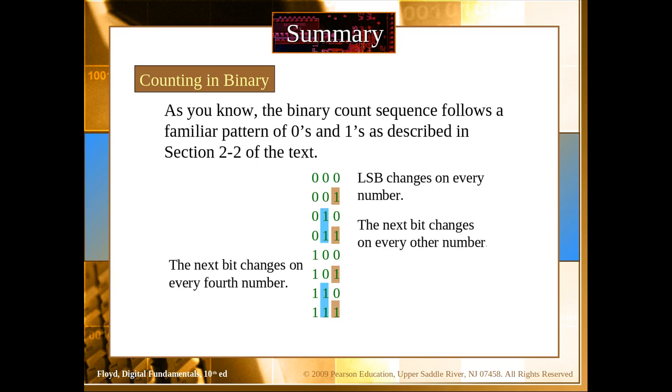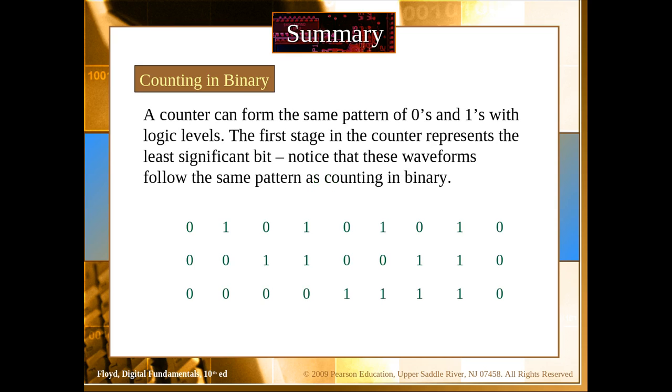Similarly, the third bit would change after every 4 numbers. And if there is a fourth bit, then it would change after 8 numbers. So it's always 2 raised to the power n, where n is the position of the bit counting from the start. This would make our life easier to design a counter, because now we know the pattern, so we can design a counter using flip-flops, as we have seen before.